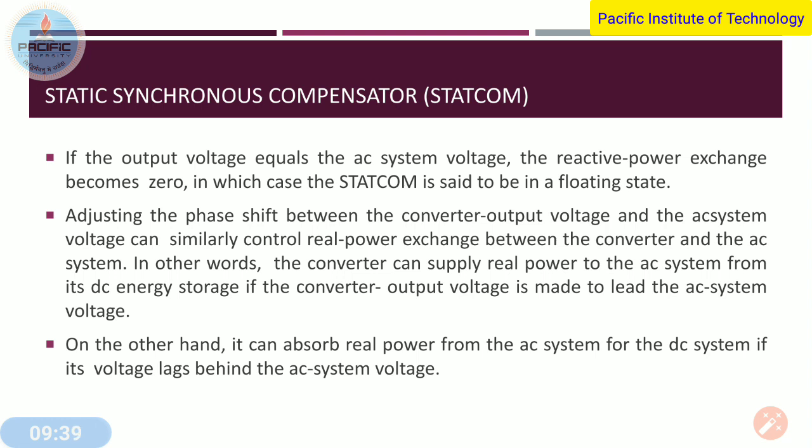Also, it can absorb real power. The converse is also true. It can absorb real power from the AC system for the DC system if its voltage lags behind the AC system voltage.